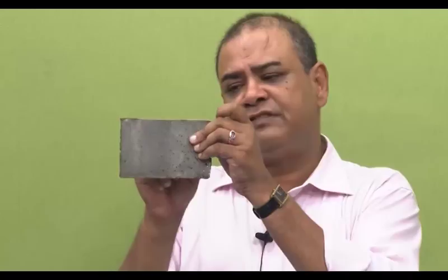So, that is why pitting corrosion is so dangerous: it will not give you any signal before a fracture happens. Though we are able to see these big holes, sometimes these holes are so microscopic that unless you go under the microscope you will not be able to see them, but actually they have punctured and reduced the cross section thickness. So, this is a severe form of corrosion when we talk about the 8 forms of corrosion. So, let us stop for this lecture, and we will continue this subject in our 6th lecture. Thank you.